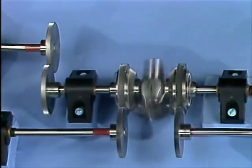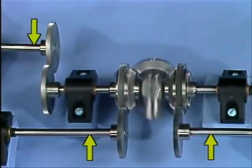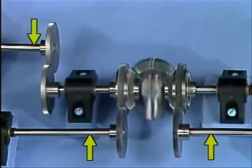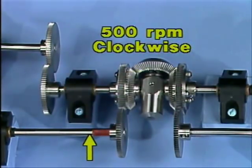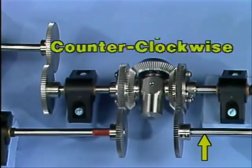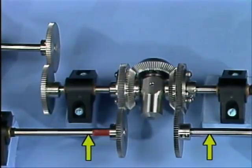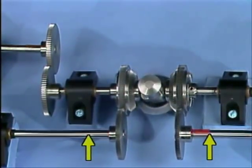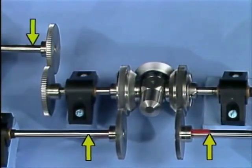Right now, this differential is comparing the speed and direction of rotation of each of these two inputs and providing a corresponding output on this shaft. To get a better picture of how the differential compares inputs, let's change the speed and direction of rotation of these two shafts. We'll rotate this shaft at 500 RPM in a clockwise direction, and this shaft at 500 RPM in a counterclockwise direction. In other words, we'll provide inputs that are exactly opposite. Since the inputs are exactly opposite, they cancel each other out, and the differential provides no output.